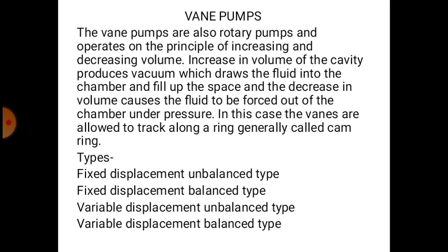So the vane pumps are also rotary pumps and operate on the principle of increasing and decreasing volume. Increase in volume of the cavity produces vacuum, which draws the fluid into the chamber and fills the space, and the decrease in the volume causes the fluid to be forced out of the chamber under pressure. In this case, the vanes are allowed to track along a ring, generally called cam ring. Types of vane pumps: fixed displacement unbalanced type, fixed displacement balanced type, variable displacement unbalanced type, variable displacement balanced type.